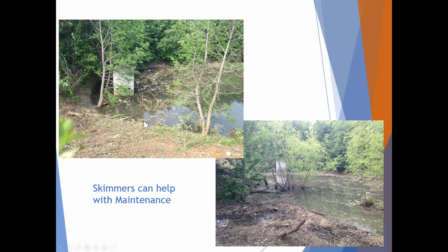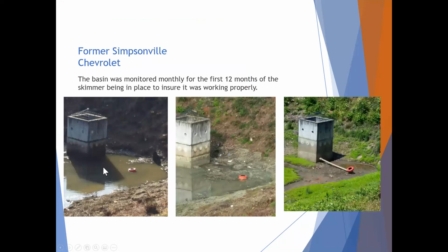So when we got here, we helped the owners get it brought back into compliance. Basically we had to get guys out there to harvest timber out of it and get it cleaned out. And when we did that, we noticed that something didn't look right because it was holding water and had these orifices here that you can see kind of through the limbs, but it didn't have a low flow orifice. And so we did some more investigating and found out that underneath this, you can kind of see it in this picture on the far right,